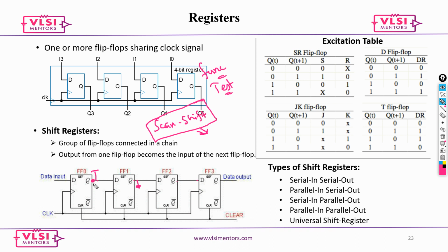That means we are serially shifting the data. Simple, right? So you give 0 1 1 0. Now this gives 1 1 1 1. So will this chip work? This is your input data, but your output is always 1 1 1. So will this chip work? No, no. There is some structural defect in the chip. There is something called a manufacturing fault that actually happened.